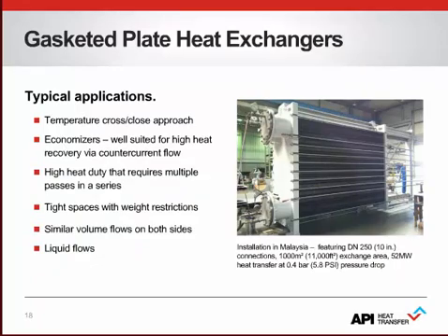Where do you use a gasketed plate heat exchanger? As we have seen, the strength of the plate heat exchanger is the high efficiency. Therefore, they are typically used when there is a close temperature approach or even a crossing in temperatures. Economizers typically demand these kinds of temperature profiles, as the aim is to gain as much heat as possible by cooling a fluid after some treatment.